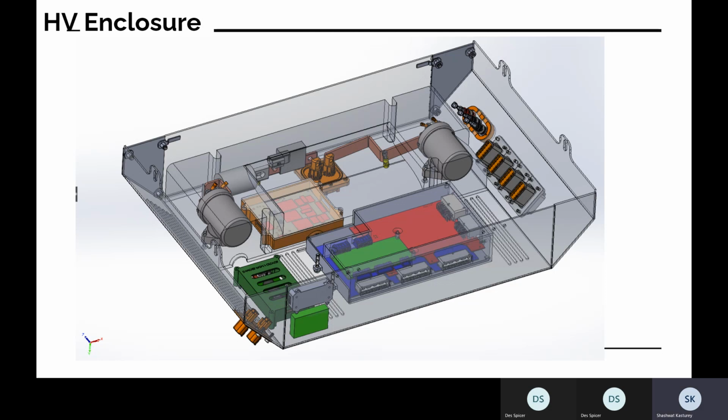So what happens if your batteries get too low? Does it just not turn on? Inside of the BMS, we can set the parameters ourselves for what we want to turn it off at. For instance, if the battery voltage hits 3 volts, we can say, turn the pack off. It's a program cutoff.